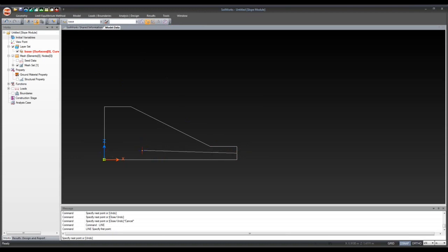Because I can't automatically snap onto the point that I want going across, and because when I move it over the line isn't perfectly straight, as you can see, there are those breaks in the line showing that you're going a little up or down. So turn ortho on, which will restrict you to a straight line, and then go past the point that you need, like this.